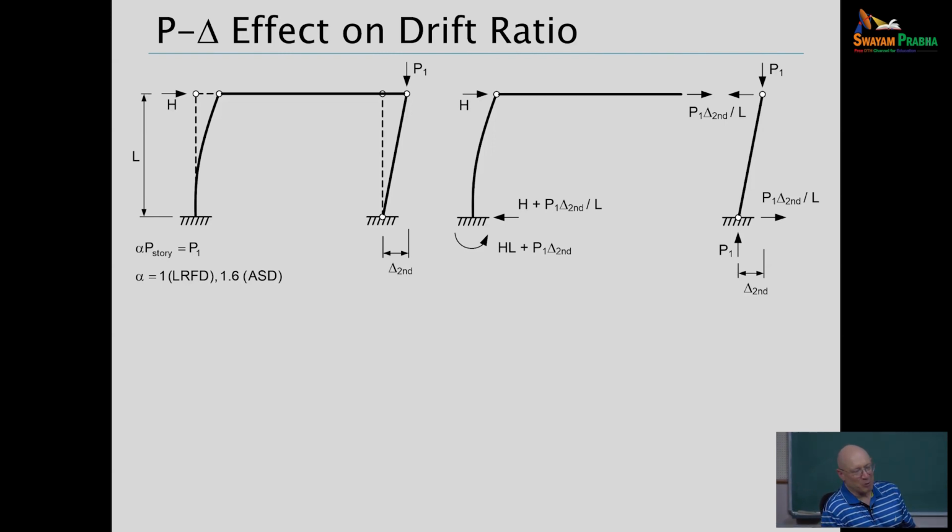And that's equal to 1 in LRFD. It means, okay, we're at strength load level when we design by LRFD. For ASD, we need to multiply by 1.6 to get to a strength load level to do our analysis to consider second order effects. Then we divide by 1.6 to get back to a working load level.